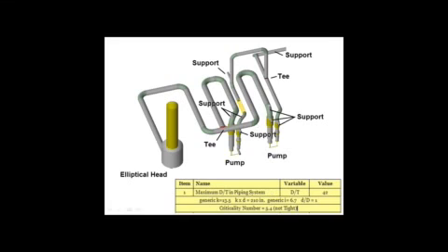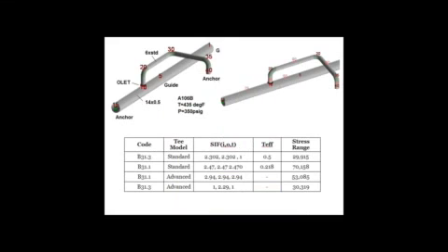The guy that designed this system knew that he had to put flexibility in to keep the loads off the pumps. So there's a ton of straight pipe here in the loaded directions. So these are definitely not tight piping systems. Now the interesting thing that affected this was the details of the supports. And the details of the supports are something that a good analyst needs to take a look at. And FEA tools isn't going to help you with that. You've got to have a good experienced designer put the supports in the right place for that system to keep the pump loads reasonable and to build them properly.